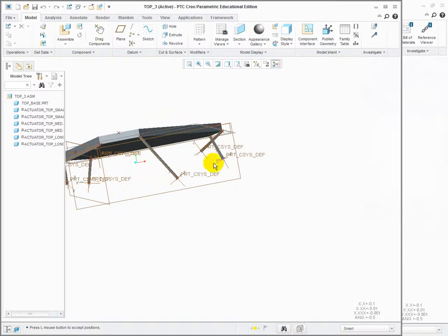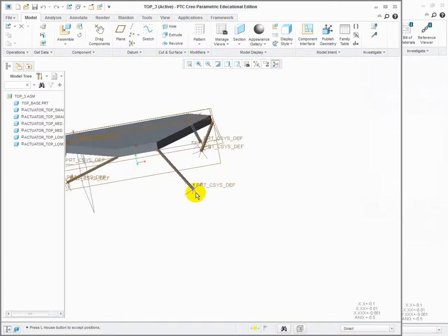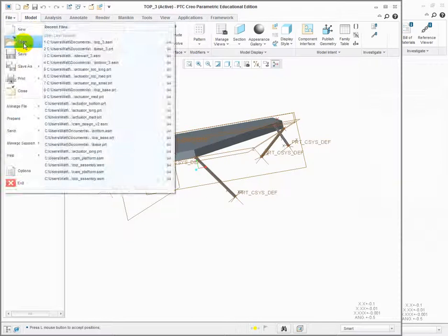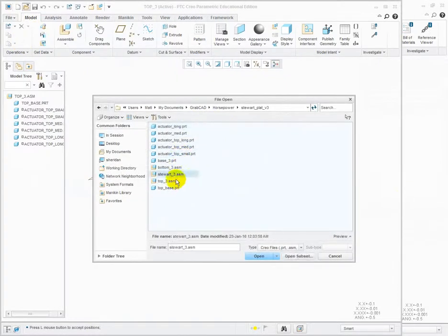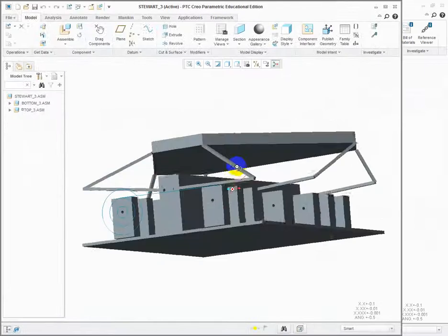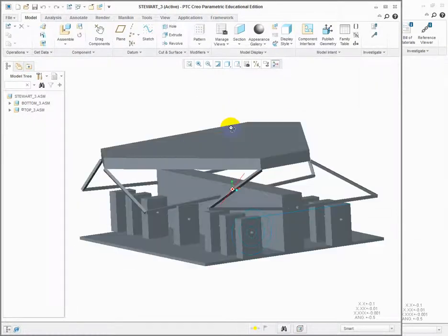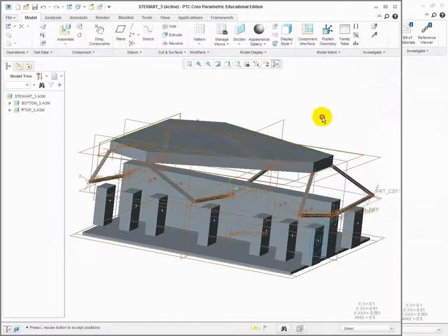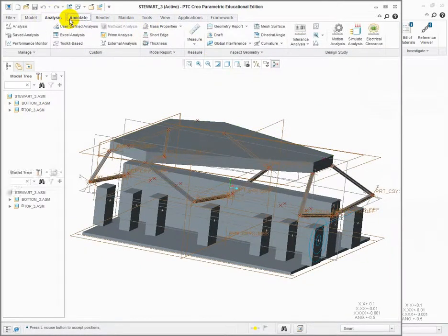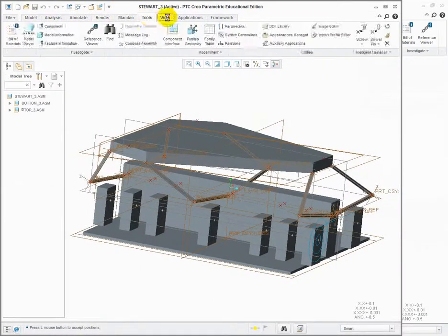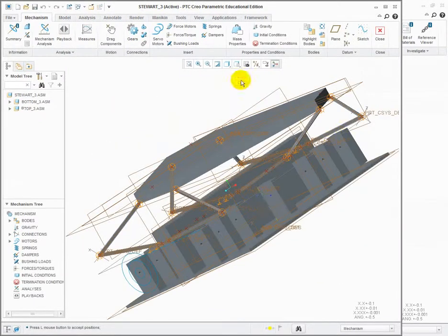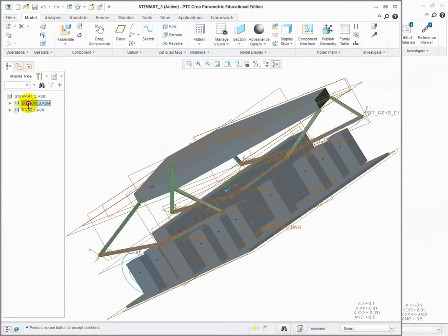Now, when I tried to assemble each of the points individually, or each of the rods individually, in Creo mechanism, it would not load. So I actually made a top half and a bottom half, and then assembled them together in this file. A lot of times with the sewer platform in particular, there's a problem with one of the last ball joints connecting. So again, I can re-show how to do that.